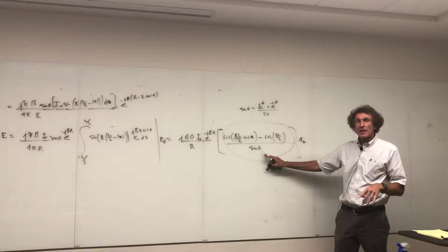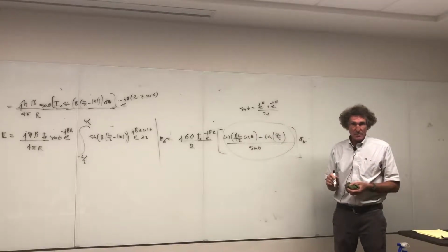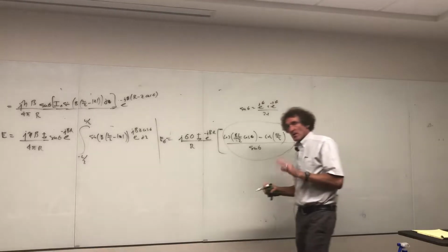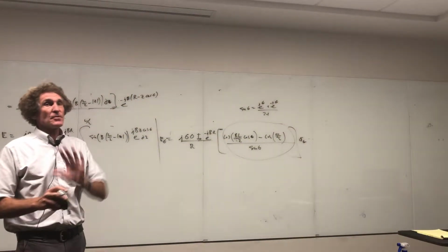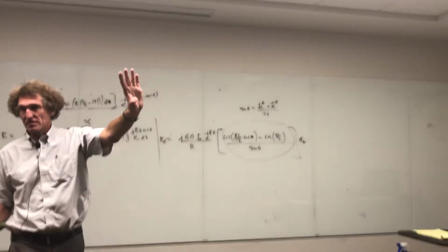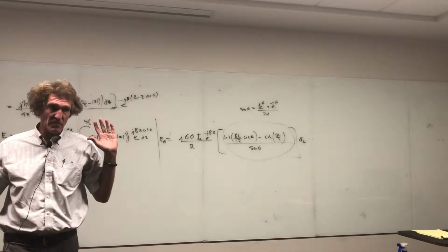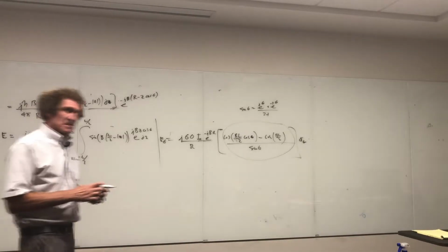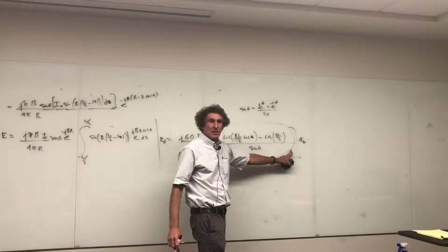Now, that right there is the E field, not the power pattern. All right? It's not the power pattern. When you do the power pattern, you could take 1/2 the real part of E times H conjugate. We'd have to get H, correct, class? Or the way I told you, if you're in free space, what did I tell you to do to get power density? 1/2 magnitude of the E field squared over eta, right? Or 1/2 eta times magnitude of the H field squared, right? Either one does it. And since this is free space, you can do it that way. But what that'll do is square this angle.